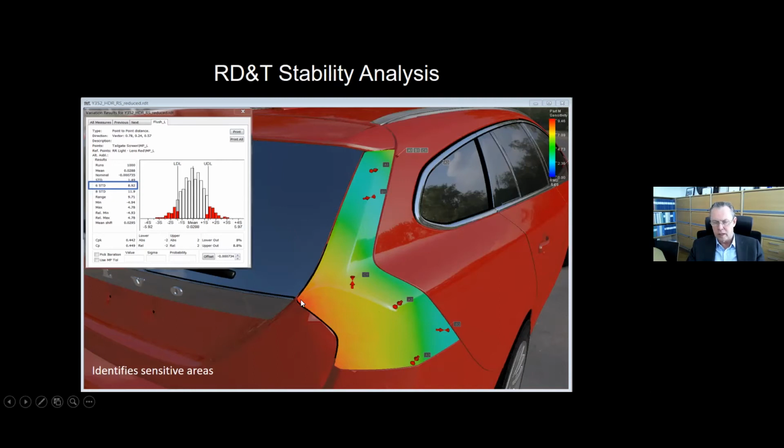So in this case, I have in the red area 9.46. It means that if I have a 1 millimeter disturbance in those red arrows, the contacts between those two parts, I get almost 10 times amplification in this red area, which is not good.